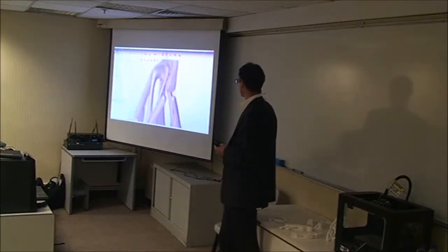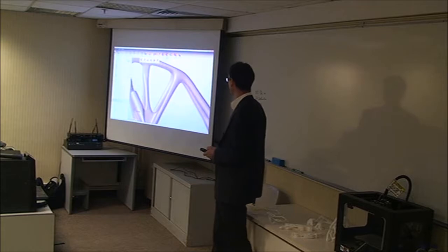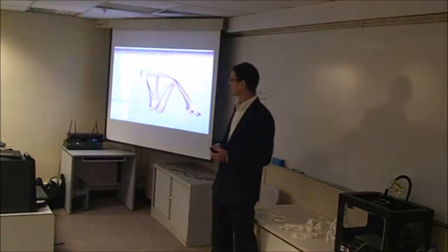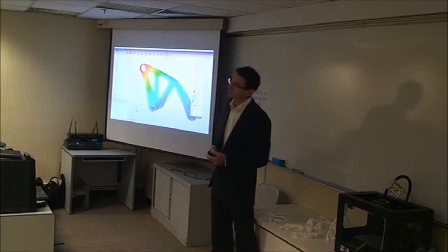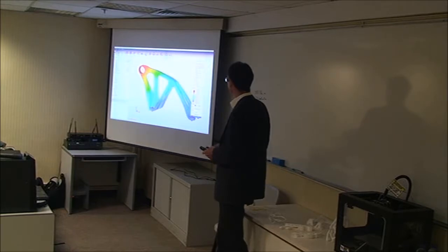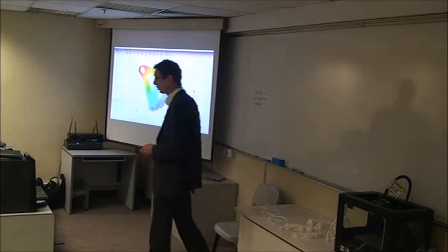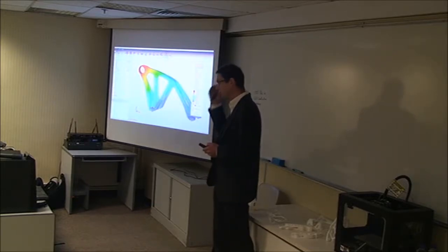And the next step is when you generate this geometry out of an optimization proposal from an optimization tool, you want to check whether it's really working like you want to have it. And therefore you directly apply the loads, the load cases you should have used before for the optimization in the first step, and you get the stresses and the deformation directly in the same tool. And when you're satisfied, then you can go into the print process. If you want to modify it, then you can modify by hand, adjust it, or you can redo the optimization or adjust some optimization parameters, because there are a lot of options to guide and to tune the optimization process.